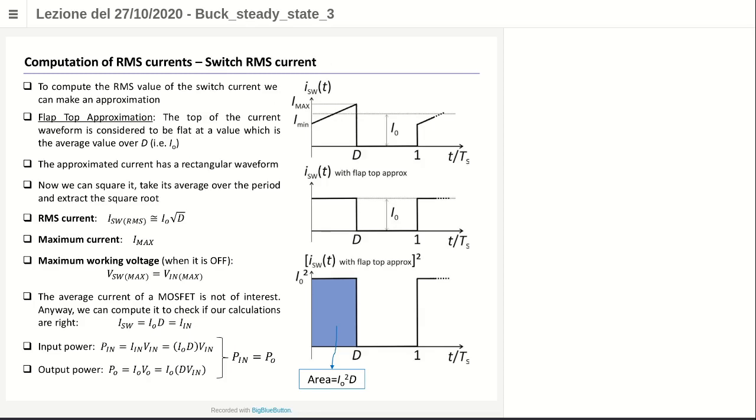Okay, no problem. Let me summarize what we did in the two previous lectures. We started talking about the buck, which is one of the fundamental topologies of switch mode power supplies. We started to talk about the CCM operation mode of the buck converter. We derived a value for the inductance L which makes it possible to operate in CCM. Remember, L higher than a certain expression, which involves the duty cycle, the load resistance and the switching frequency. Then we learned something about real components.